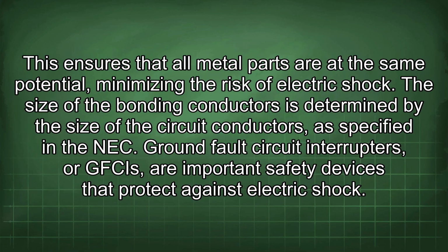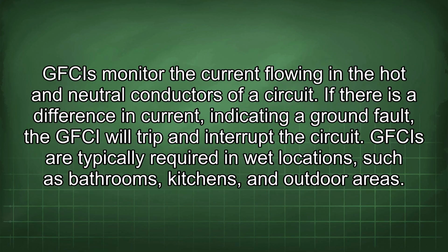Ground fault circuit interrupters, or GFCIs, are important safety devices that protect against electric shock. GFCIs monitor the current flowing in the hot and neutral conductors of a circuit. If there is a difference in current indicating a ground fault, the GFCI will trip and interrupt the circuit. GFCIs are typically required in wet locations such as bathrooms, kitchens, and outdoor areas.